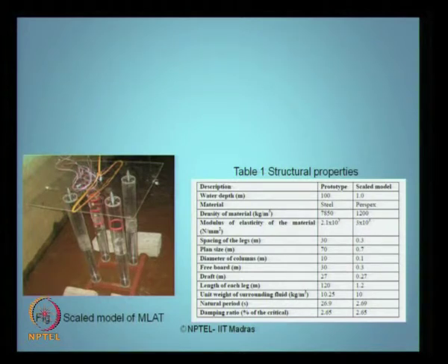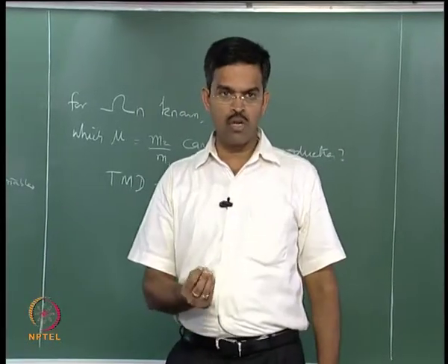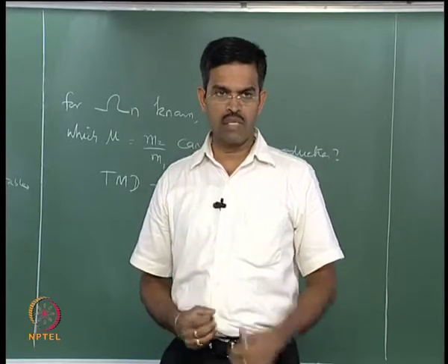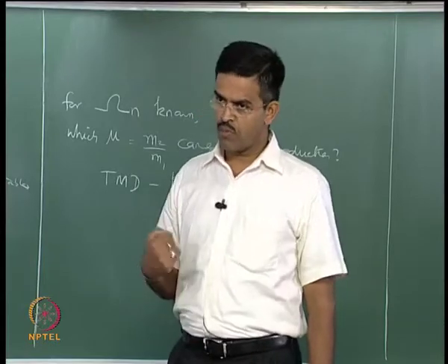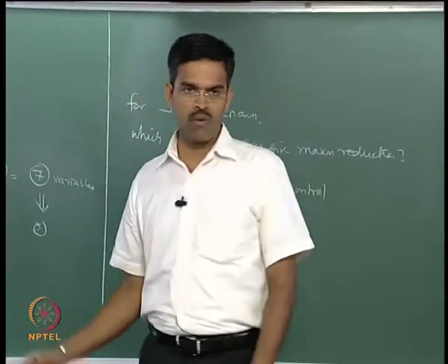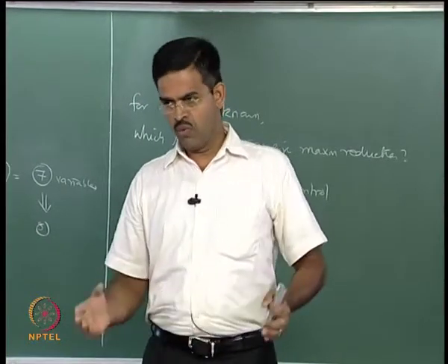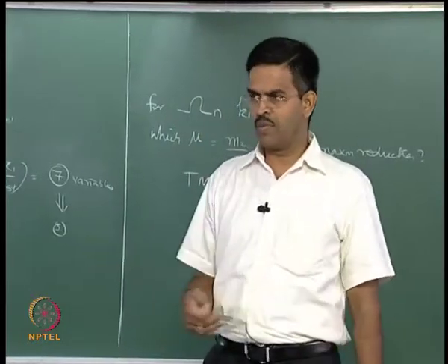You may wonder why a more intrinsic scale has not been attempted. It is because of the limitations in terms of attaching the mass. I am looking for a mass ratio of 0.01 onwards. If I go for a larger scale, I will not be able to operate the upper mu ratios. If you go for a smaller scale, I will not be able to operate the lower mu ratios. So, I picked a scale model which can accommodate my mu ratios, that is the mass m to m1 ratio, which can suit my experimental setup.